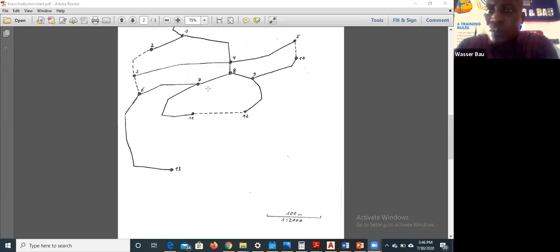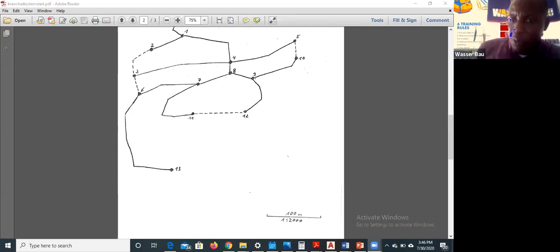In the short term, you loop because if there is water failure in one area, for instance, if there is failure coming from node 9, then water can flow from node 7. Or if there's maintenance midway between 9 and 10, the water will not flow to node 10. But because I have designed the network as a loop system, water can easily come from node 5 to 10.